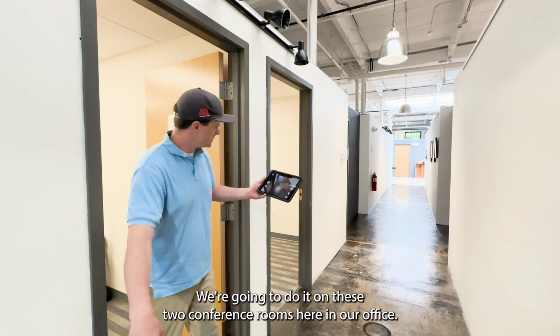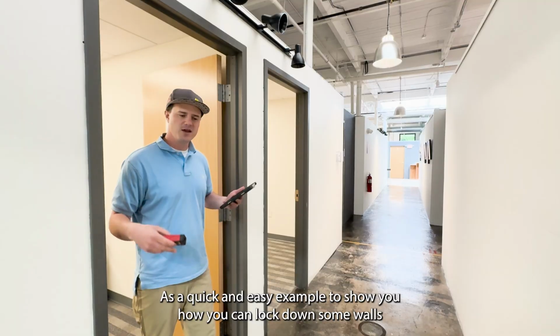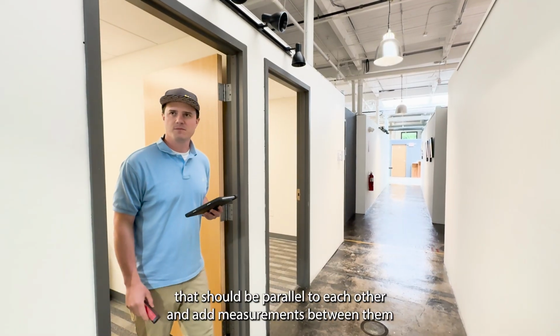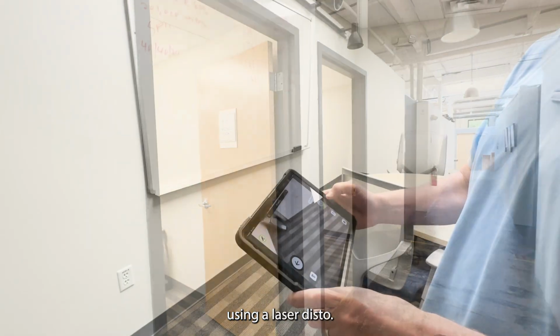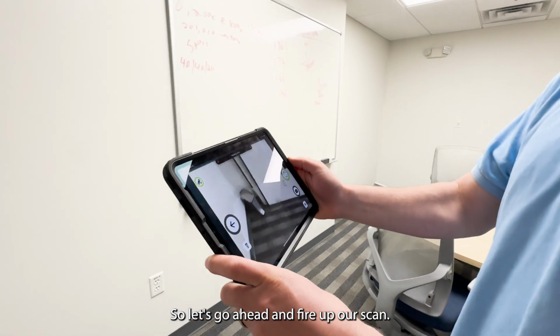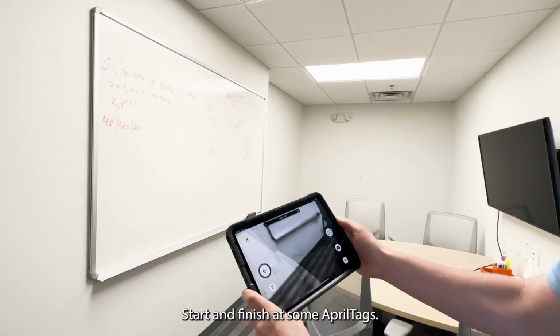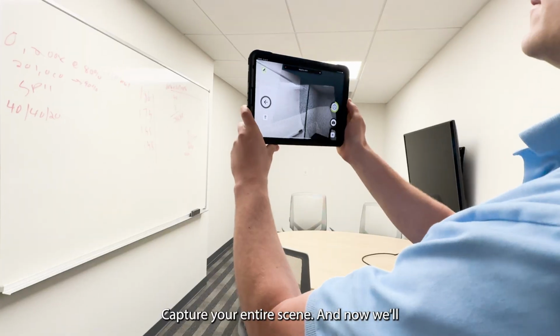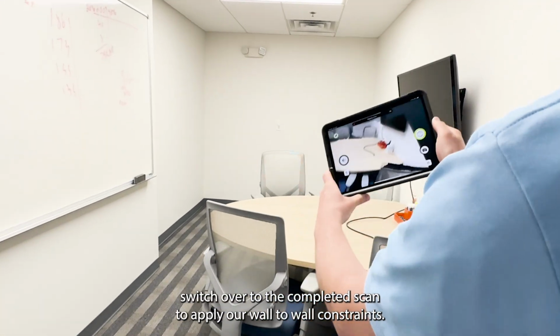So we're going to show both of those options here today. We're going to do it on these two conference rooms here in our office as a quick and easy example to show you how you can lock down some walls that should be parallel to each other and add measurements between them using our laser disto. So let's go ahead and fire up our scan. The actual scan process here is standard. Start and finish at some April tags, capture your entire scene. And now we'll switch over to the completed scan to apply our wall-to-wall constraints.